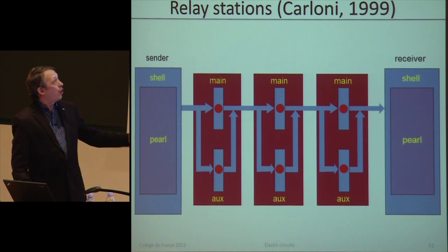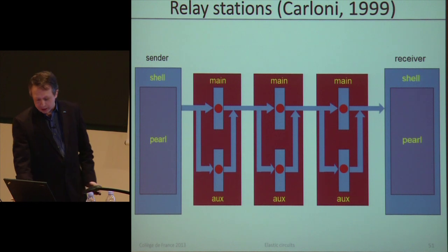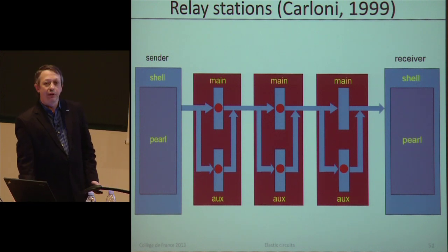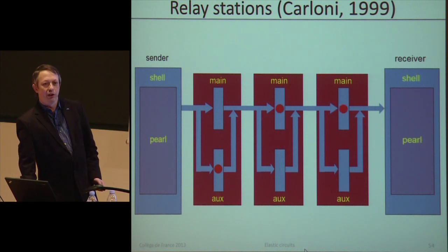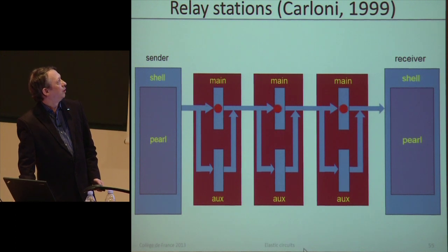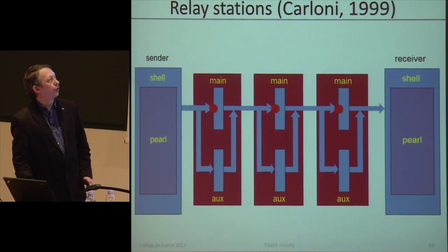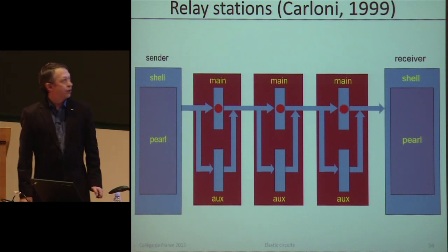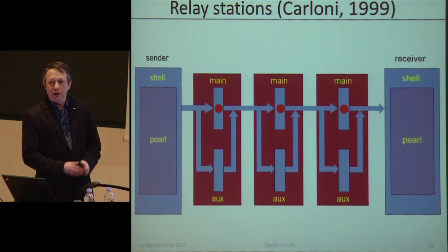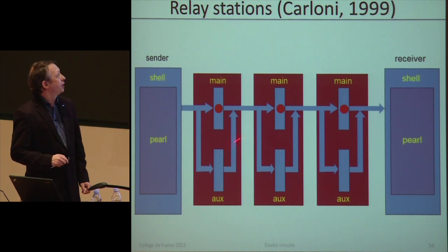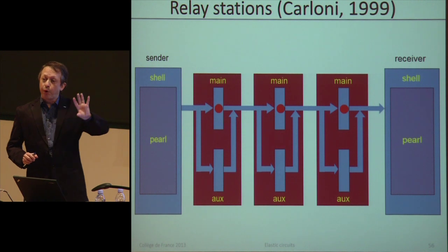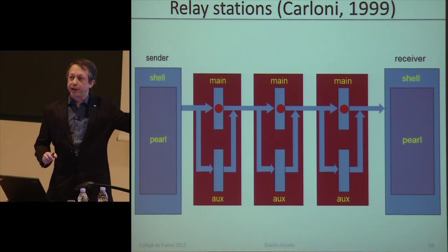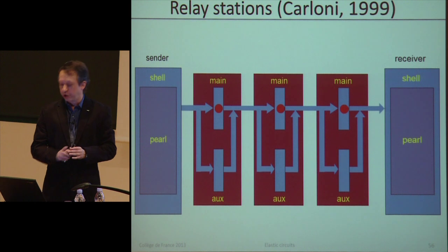Okay? Now, when the receiver is able to receive more data, then this data is delivered in the same order as it was sent by the sender. Okay? And the order is recovered, and then we go to the normal operation. So the interesting idea here is that basically we need this double storage capability just to propagate the back pressure cycle by cycle without having long combinational paths.